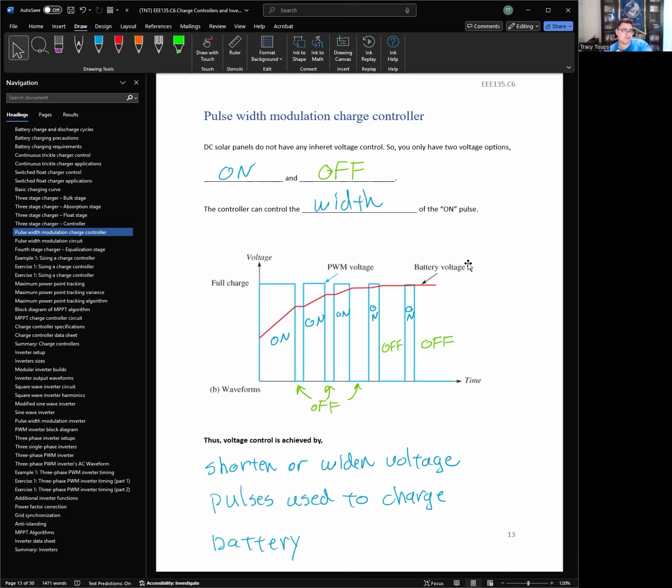Now the question is how do you control the voltage, right? Well, if I want to go from 10 volts to 5 volts, what can I do? Well, one person would say, well, let's just put 2 resistors and do a voltage divider. Technically, if you do that, that's an incredible waste of energy. 50% of your energy can get thrown away because you're doing resistor division. That's a terrible idea. We don't use voltage dividers with resistors to lower voltage in today's world.